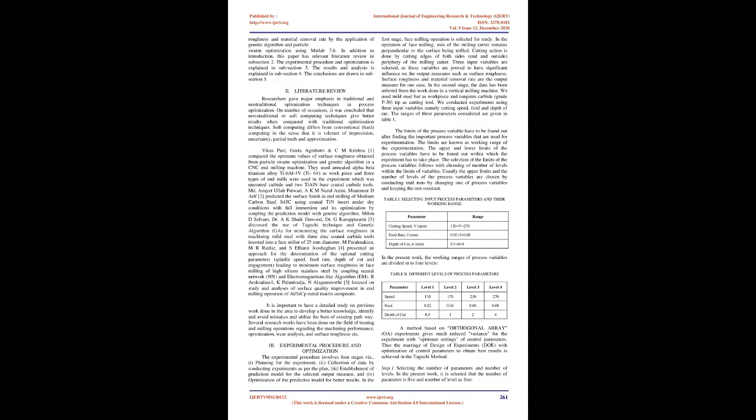Krishna [1] compared the optimum values of surface roughness obtained from particle swarm optimization and genetic algorithm in a CNC end milling machine. They used annealed alpha-beta titanium alloy Ti6Al4V (Ti64) as workpiece, and 3 types of end mills were used in the experiment, which were uncoated carbide and 2 TiAlN-based coated carbide tools.